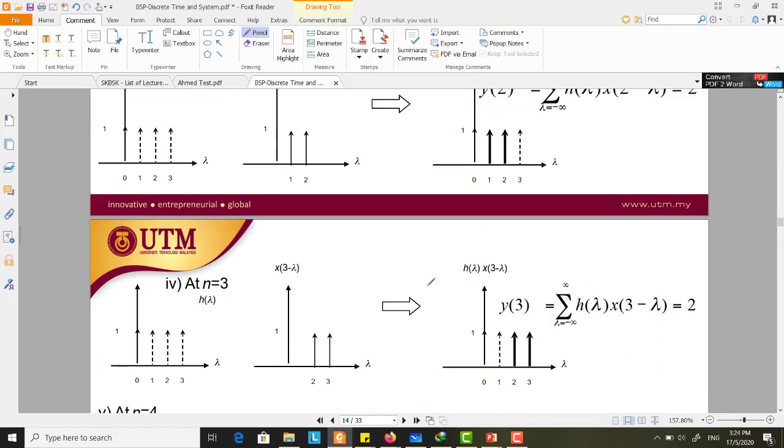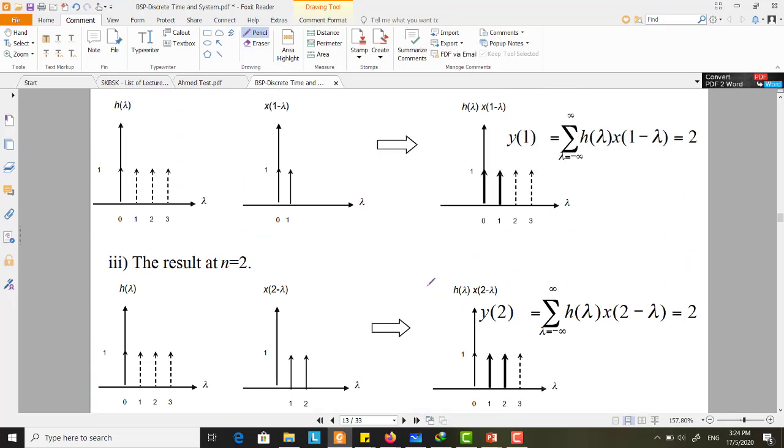As you can see here, the translation or shifting operation needs to be done in order to compute the convolutional operation in one dimension. So that's why, when we discuss convolution in CNN, which is a two-dimensional signal, you have a process of translation from the upper left corner to the bottom right corner. The translation happens because that is the nature of the convolutional operation.